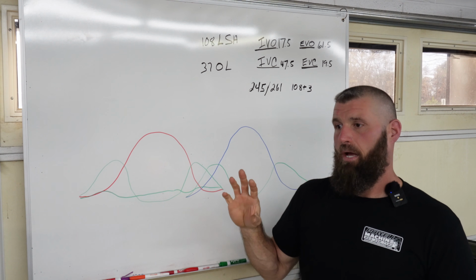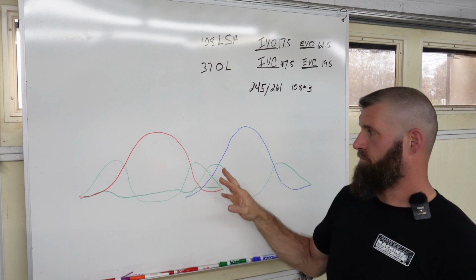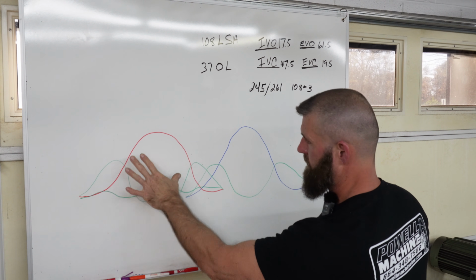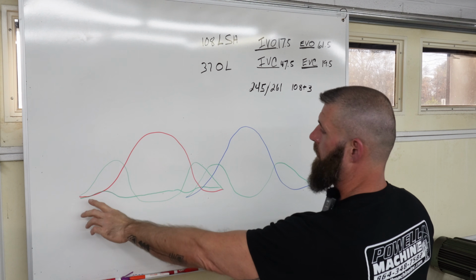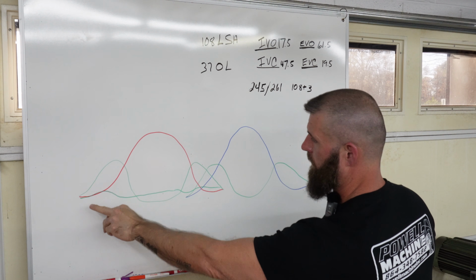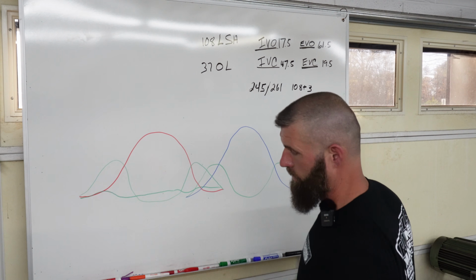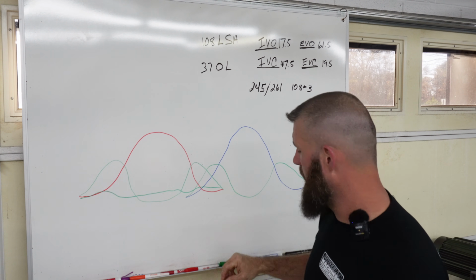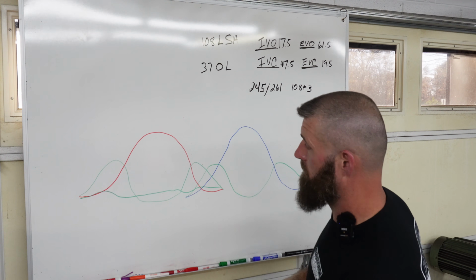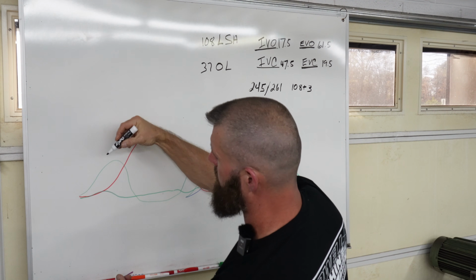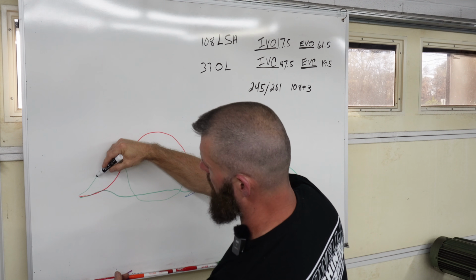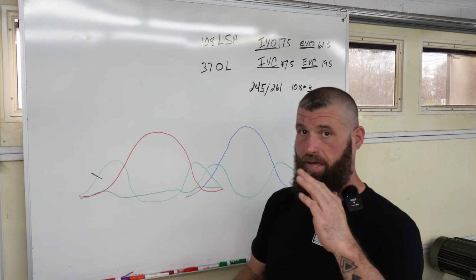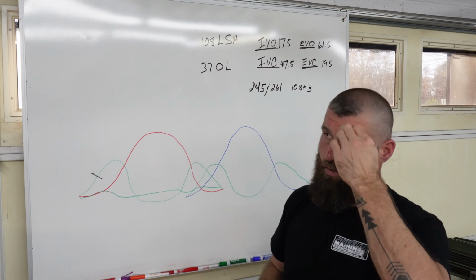But what we talk about, and I've done some chicken scratch drawings here. Red is the lift curve. This is the exhaust lobe, intake lobe. The green line is the acceleration curve, and this green line is the jerk curve. So let me mark here. Say this is a hydraulic, right? Somewhere along in here is 4/1000ths lift. So that's where the system starts.